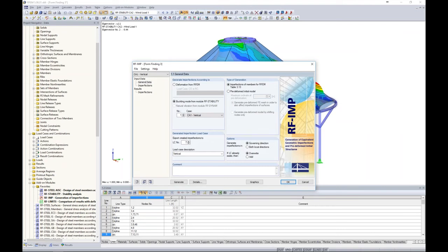Now, imperfections can be related to the AISC, Chapter C, the direct analysis method, where the code tells us that if we want to apply things like notional loads, for example, to account for column out of plumbness or member out of straightness, for example, we can apply imperfections and manually model these type of imperfections.